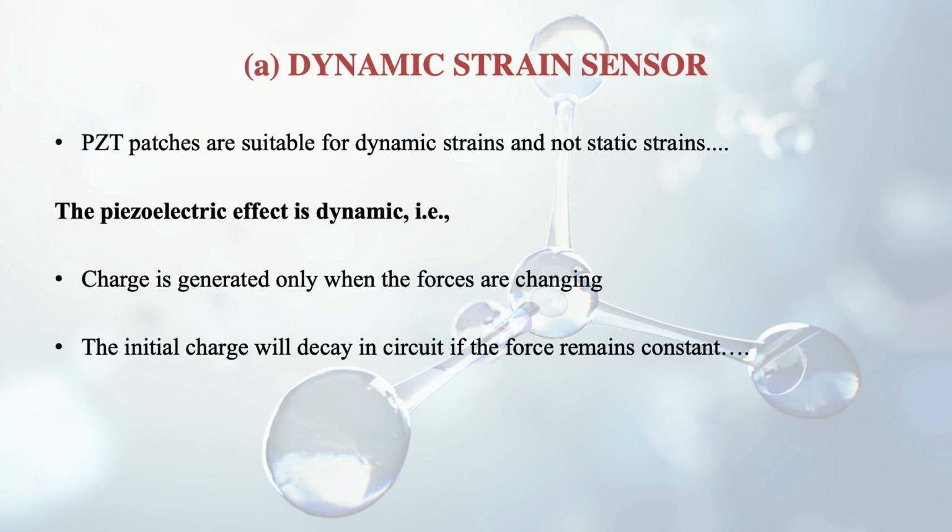The initial charge will decay in the circuit and then the voltage difference or the potential difference will go down to 0. So they are not suitable for static stresses. Typically in the case of dynamic strains, we have found through our experiments that frequencies as low as half or 0.5 Hz can be easily measured by PZT patches.